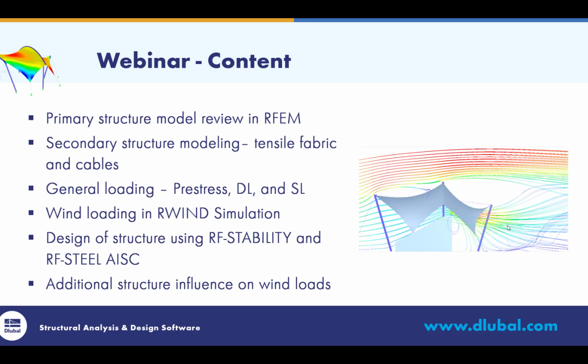So regarding the content for the next hour today, I want to give a brief overview of the primary structure that I've already modeled in our finite element analysis program, RFEM. For the sake of time, I went ahead and modeled that primary structure, but what we will be doing together is modeling the secondary structure, and this would include the tensile fabric membranes as well as the boundary cables.